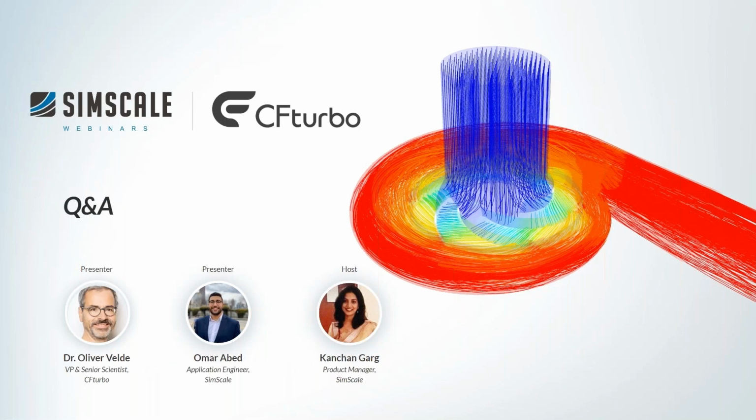But it really is up to you. If you wanted to conduct a mesh sensitivity study, for example, you're able to kick off all the simulations in parallel for different mesh fineness levels, where you can go about it in different ways, whether you work with the automated 1 to 10 scale, or if you wanted to define the different parameters corresponding to the global fineness or local fineness of the mesh that you're working with. So really just up to you. It's either something you can parameterize within a table, or just as fast as you can set it up and push them to run.